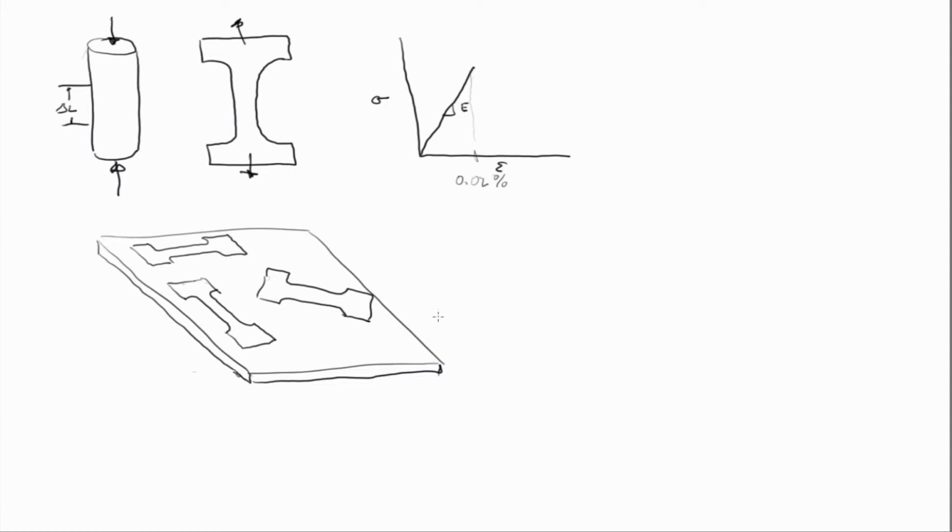Right? And so if this is in fact a steel, what you'd see is if I continued to strain it, I'd get into a region like this. And we call this so-called plasticity or inelasticity. Okay? And we call it plasticity or inelasticity because any strain beyond this point, and this is called the yield point, is permanent.